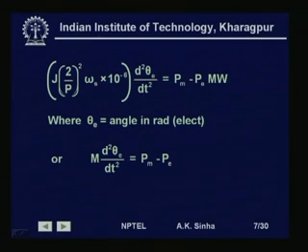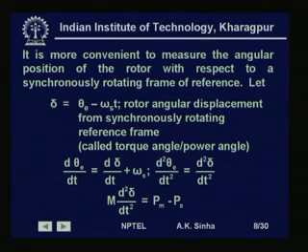With respect to a synchronously rotating reference frame, this value of theta will be much smaller, and it will not keep changing unless there is a change in the speed of the rotor from the synchronous speed. So, as I said, it is more convenient to measure the angular position of the rotor with respect to a synchronously rotating reference frame.